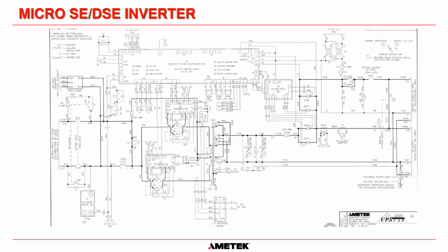And I know this drawing is very, very busy. I do understand that. But it's exactly the same drawing. This is actually one of our ferroresonant bridges. So we have our battery connected here. Okay. There is the center tie point of the transformer there. Like I said, I know it's very difficult to see, but we have Q1 and Q3 here, and we have Q2 and Q4 here. So if we switch this pair of IGBTs on, we will go through this way, through the transformer and back to negative that way.